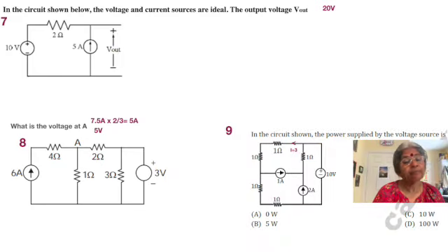So we have the remainder as I plus 2 flowing in the lower two 1 ohm resistors. So that gives rise to another 2i plus 4. Now 6 plus 4 is equal to 10, so I is equal to 0. Obviously I is equal to 0, which means that the 10 volt source is just keeping the potential across the top node and bottom node as equal to 10 volt, but it is supplying no current. So the power delivered is equal to 0.